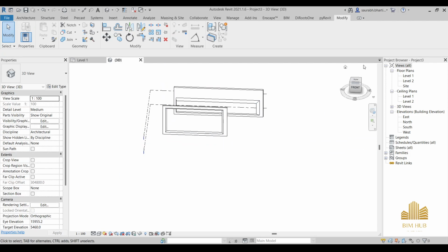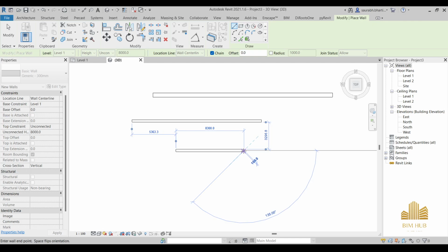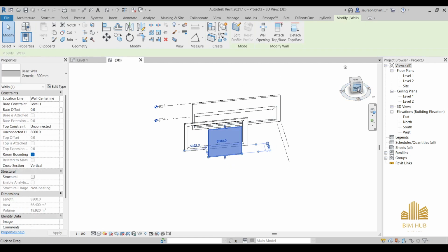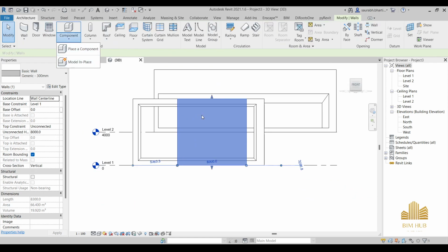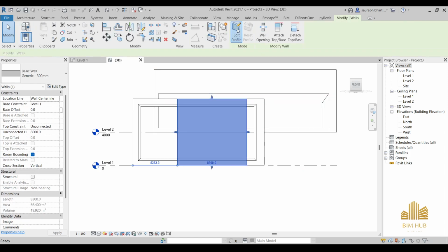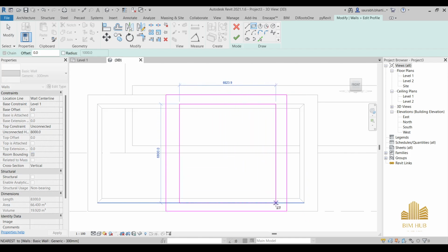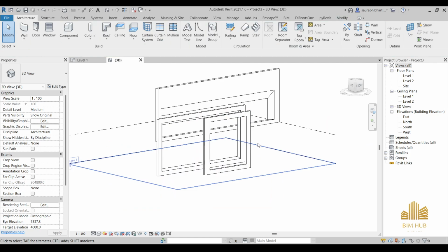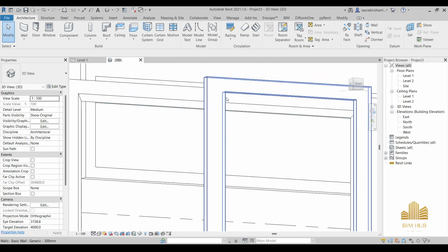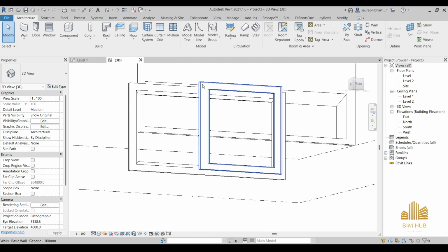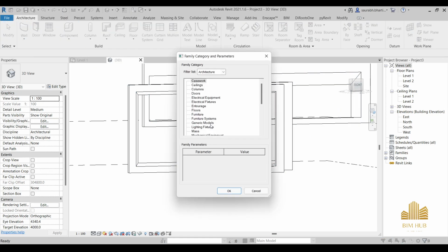Finish model. After this, what other option do we have? The other option is, go to this, make a new wall, go to the front, go to Architecture, go to Model in Place, and before that let's make a void in the wall. So if you are making a cut under a wall, it will look something like this. Now you can see you have a void, and then you have to make an angular surface over here. In this one, I'm just gonna make an angle on the top and nowhere else. So here you can go to Component, Model in Place, Generic Model.